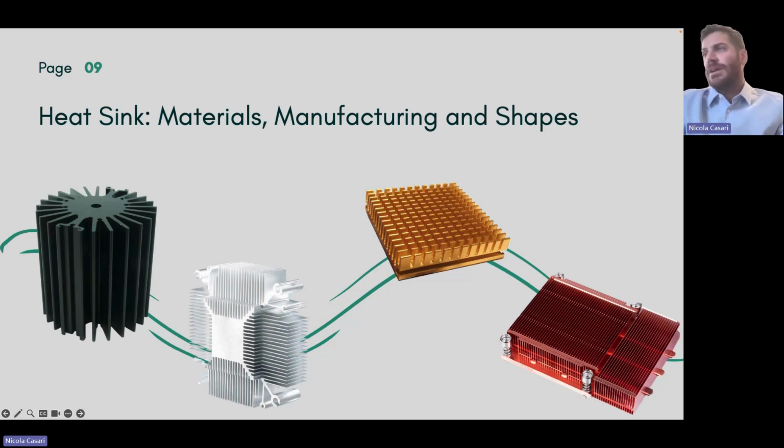By far the most common heatsink is extruded aluminum, and this is very good, but it has, of course, some limitations. We can go to skived heatsinks in case we need better performance, or even CNC machined heatsinks are often used. However, these devices might vary a lot in terms of cost, performance, and also directionality of their performance. So, for example, we see a number of elements here.